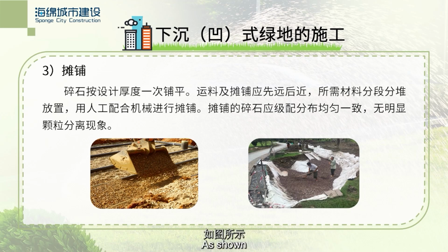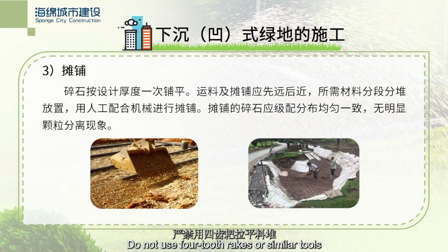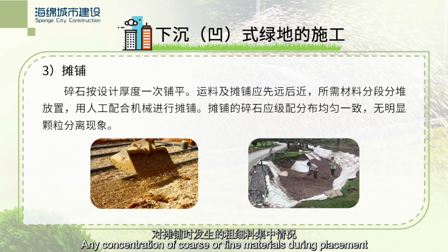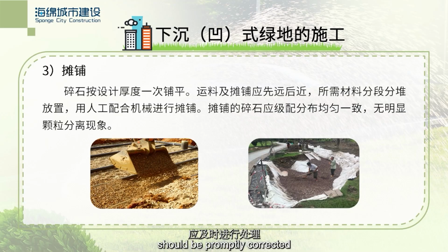As shown, the gravel should be uniformly graded, with no obvious particle segregation. Do not use 4-tooth rakes or similar tools, as that can cause localized concentration of coarse or fine materials. Any concentration of coarse or fine materials during placement should be promptly corrected.